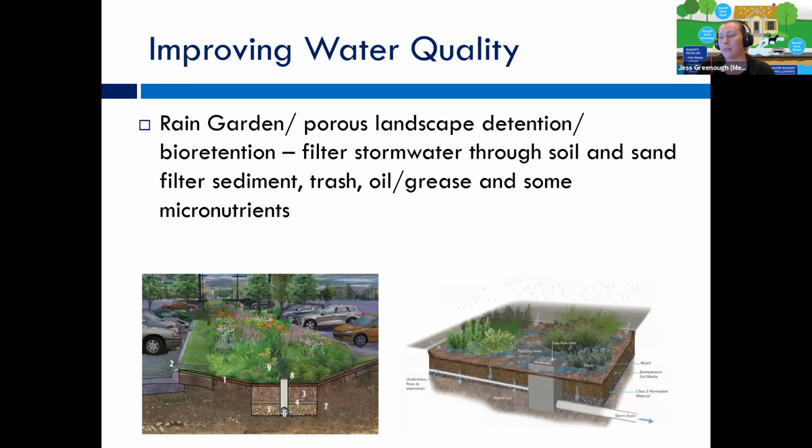We could also do something a little bit more dressed up than a grass swale, like a rain garden, where we're actually adding more plantings and letting the water stay there for a little longer. Kind of the same idea, just pulling out all of these harmful things from the water. And most of the mentors today have chosen rain gardens for their background for water quality.